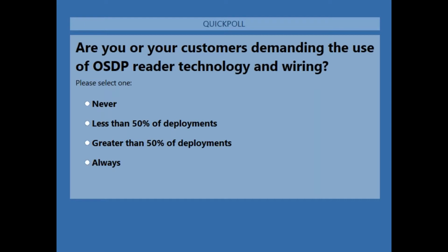Hey, Francisco, it's Jared. I did want to bring up, there is the option for addressing Allegion MT series readers using a configuration card. If you need to get a hold of those cards, you will need to reach out to Allegion directly. We don't have access to them in our price book, nor do we have the ability to get them. However, I have received a couple, and apparently they do work with the Allegion readers, so you will be able to address 0 through 3 for Allegion readers as well.